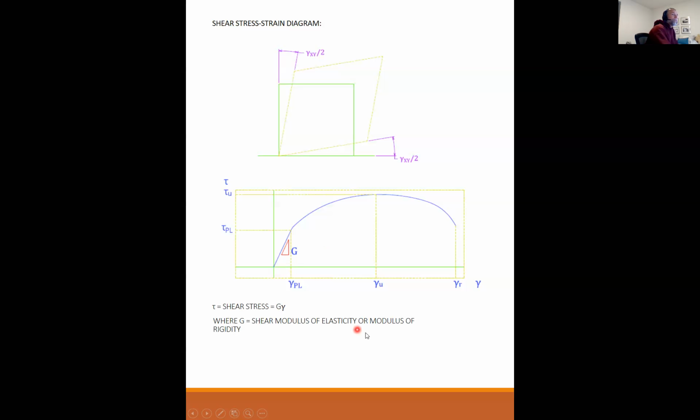And the modulus of rigidity is equal to, and I won't do this derivation, Young's modulus of elasticity in the longitudinal direction divided by 2 times 1 plus nu, where nu is Poisson's ratio. That's where it comes in to engineering properties. So the shear strain is related to the longitudinal strain by Poisson's ratio.